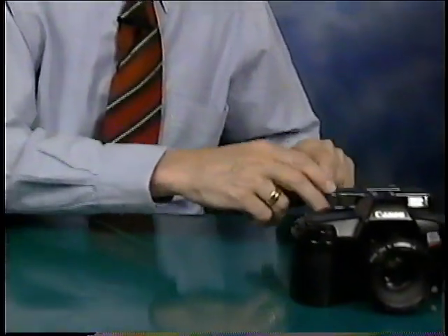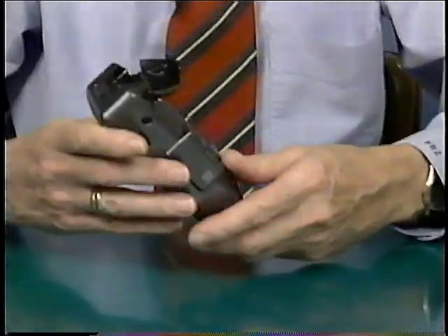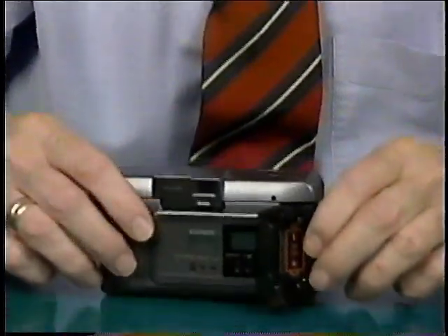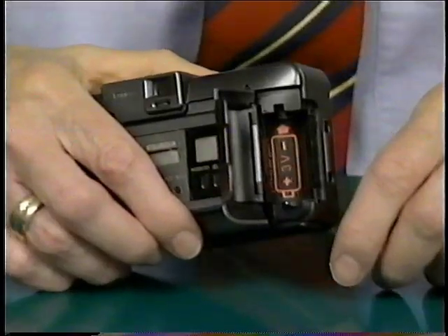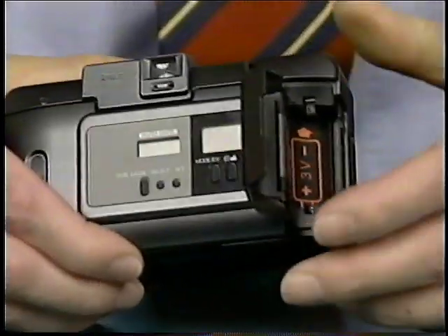Any modern electronic camera, particularly those with a liquid crystal display or LCD, are probably microprocessor controlled. And if they are, they have a specific sequence of operation. So testing them is very easy, provided you follow this sequence. And the very first step is, just like a home computer or anything else, when a battery is first installed or they're first powered up, they boot up in some way or another.